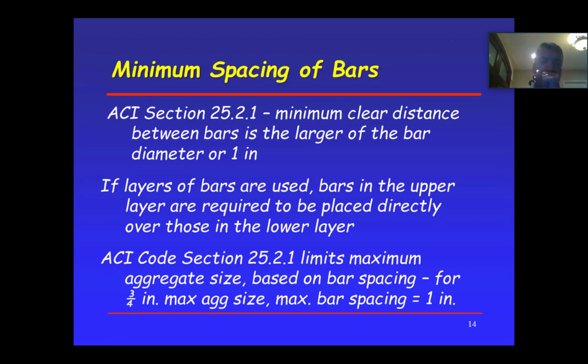We call it in practice pea gravel, because it's so small. You cannot use that in structures like buildings, parking garages, and high rises. You can use this for your patio slab, sidewalks, backyard, or walkways. The reason people do that is that when they order a load of concrete, they order a pump with it, and they have to pump it from the street to the backyard.